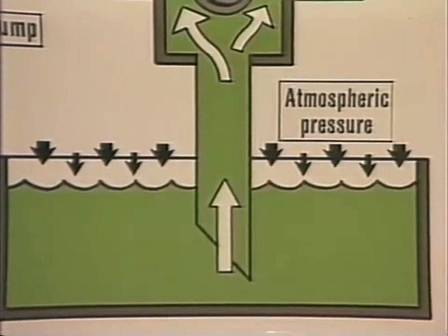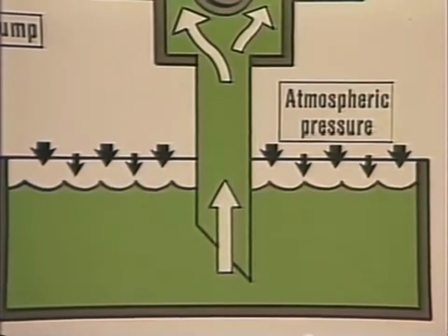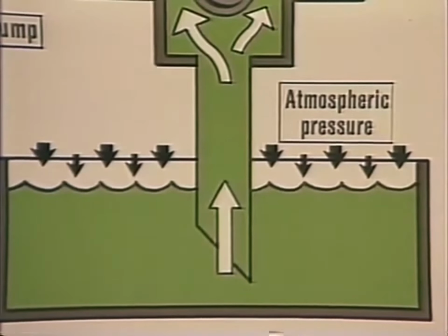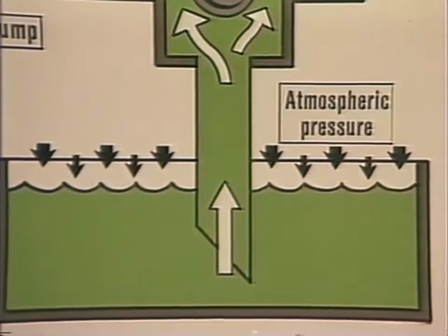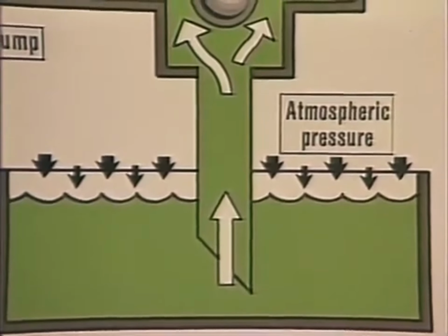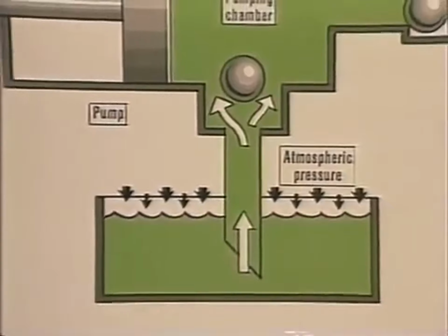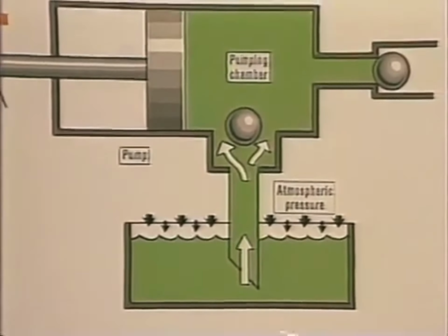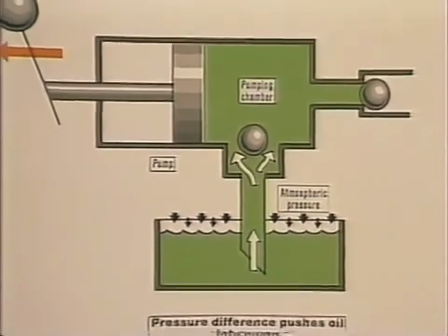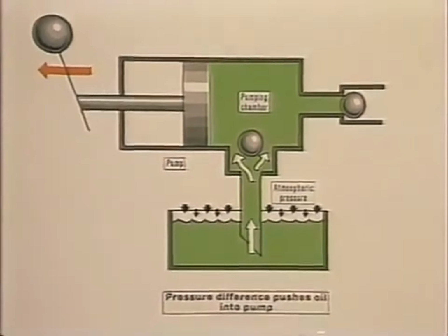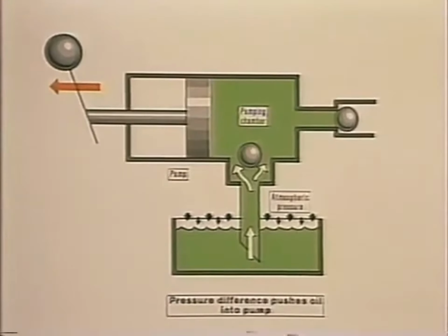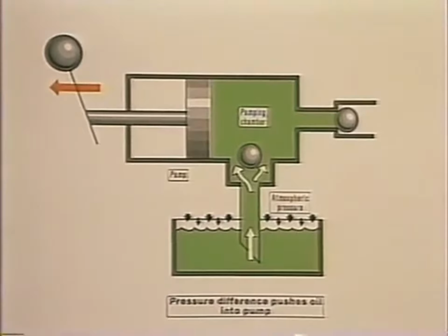bends as possible. Another thing, a surprising number of people, and probably some of you, think a pump sucks the oil out of the reservoir. It doesn't. A pump merely lowers the pressure at its inlet, and fluid is pushed in by atmospheric pressure acting on the surface. Inlet lines are especially important because with only 14.7 psia doing the pushing, any restriction or even too thick an oil may cause the pump to starve.